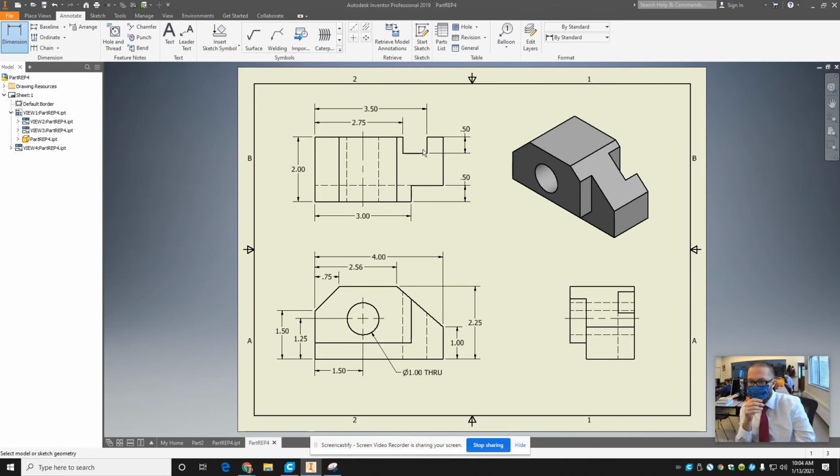All right, now last thing. Let's see. I think I need this cut out here. Right? This height. Actually, this height is already right here. No, this width. This width of this is right here. The height of this would be in this view. I do have to dimension that. The height of that cut. Again, I don't need the width of it because that's this dimension here. This is the top view, this is the front view. So that width of it is this. I think that's pretty much everything here for this one.